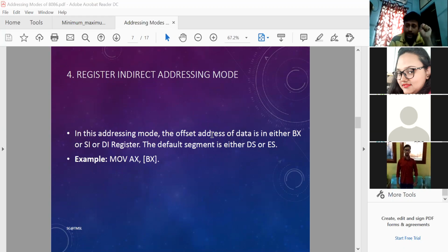In the same way, in the 8086 microprocessor, the BX register is the default. It's one type of offset register where the offset address will be stored. Now the offset address is the address that is incremented or changed by the microprocessor every time an instruction or data byte is fetched from the corresponding segment.